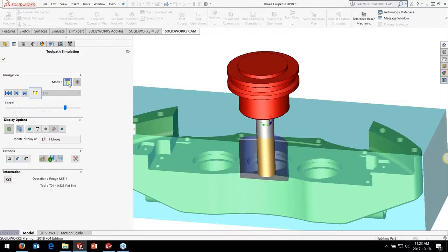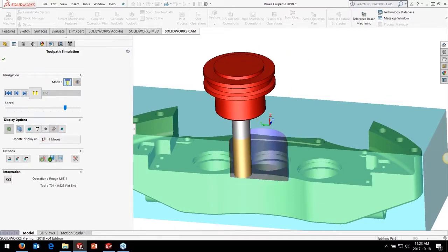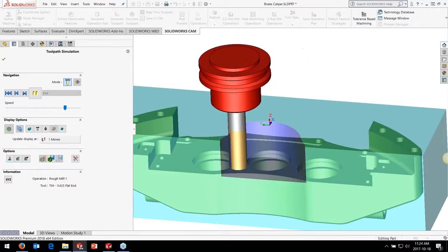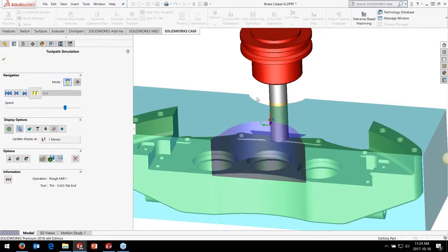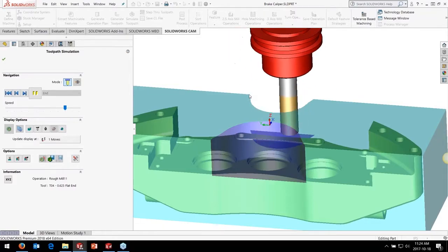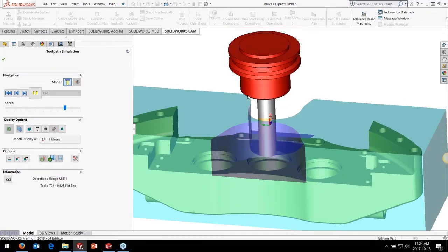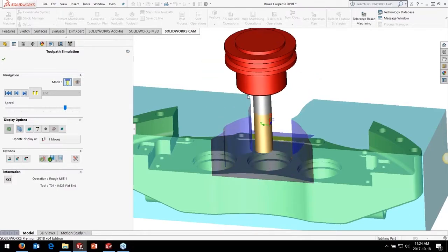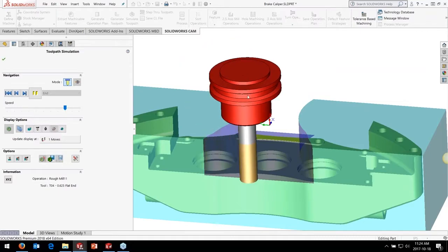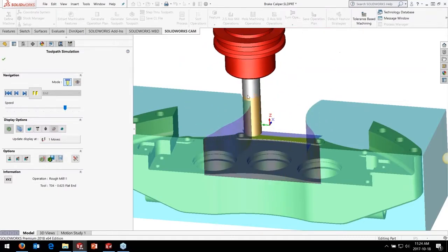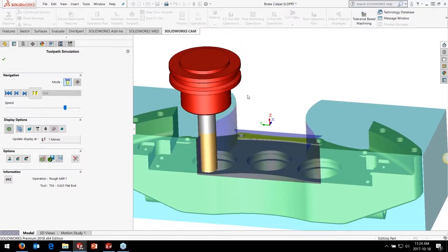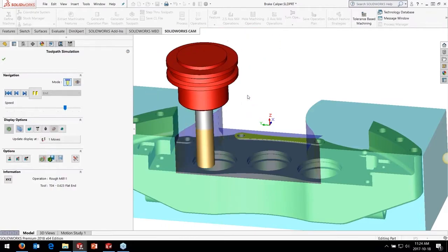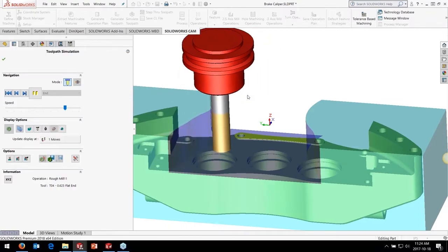There's a term in the industry called trochoidal milling, and essentially what that allows you to do is you use smaller step overs, use the full flute on the tool. So in this case, I would go and say, look at my tool, look at my flute length, it's 1.5 inches. I would go and adjust my depth of cut to 1.5 inches. And basically what it's going to do is it's going to kind of do like an elliptical style toolpath as it loops around and comes back in here. What it will do is it will kind of adjust the feed rates as it's coming in here. So if we just take a quick look at the simulation here, you'll see it'll start on the outside and kind of do this kind of sweeping elliptical motion.